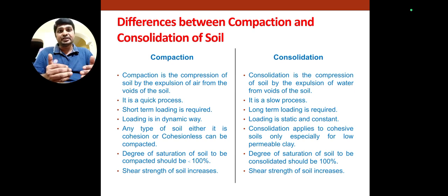Short-term loading is required for compaction, whereas long-term loading is required for consolidation. The loading is dynamic in compaction, whereas the loading is static and constant in consolidation. Any type of soil, either cohesionless or cohesive soil, can be compacted, whereas consolidation applies only to cohesive soils, such as clay or silt particles. The degree of saturation of the soil to be compacted need not be 100%, whereas the degree of saturation of the soil to be consolidated should be 100%.